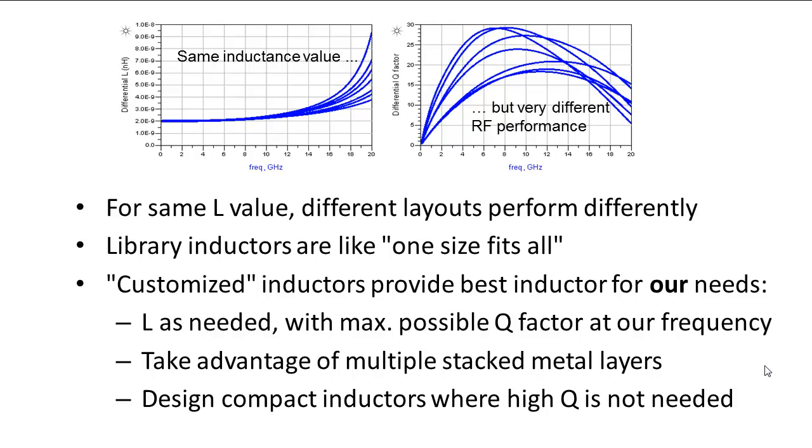These library inductors have one value at some frequency, but typically they don't have the value that you need at the frequency where you want to use that inductor. And because inductors are physically large devices taking a lot of chip space, we want to make sure that this chip space is used in the best possible way and the inductor performs as good as possible for your needs.